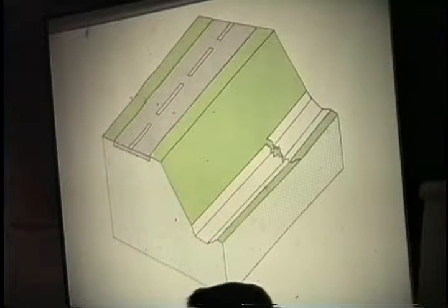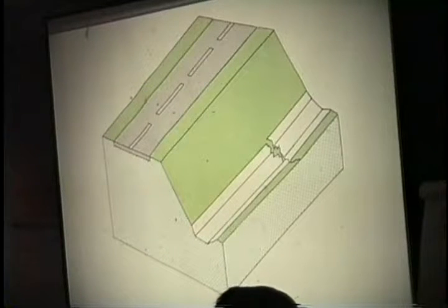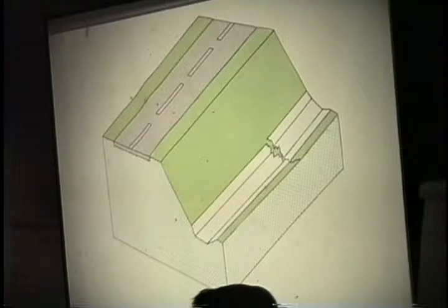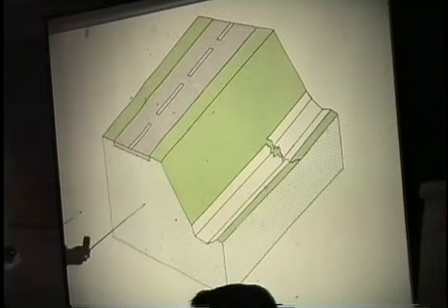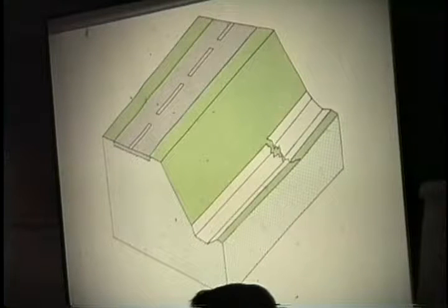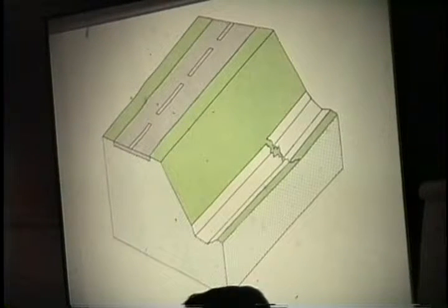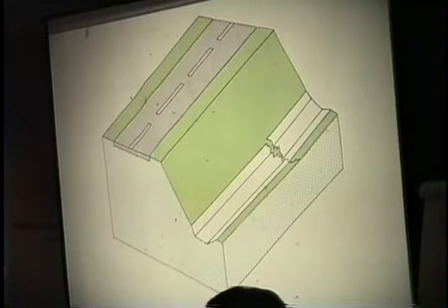How many of you folks in the maintenance yards have rolls of filter fabric? Larry, Doug? Well, materials. No big bunch. Do you use it for this kind of application? And French drains here and there? If you've got a crack in the road and water is coming up in the roadway, you can also just make a French drain across the road, intercept the water, and that sort of thing. But if you ever put in a pipe and put gravel around it, line it with filter fabric.